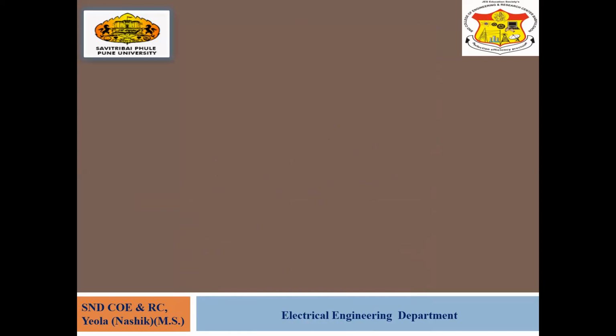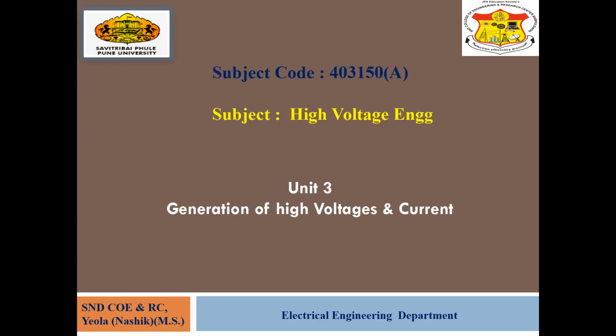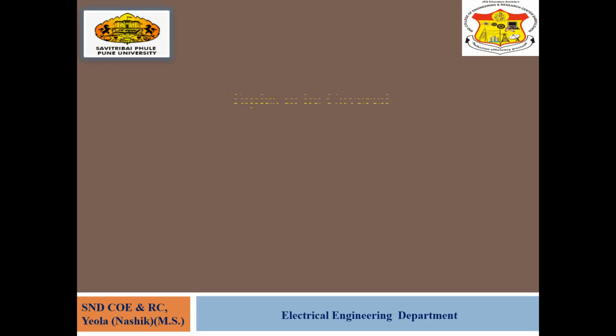So, in the last lecture we have seen the half-wave doubler circuit. It means the voltage is going to be doubled. Not exactly the same, due to the time constant of the capacitance, the voltage is somewhat less, so V output is less than 2 Vs maximum. But it is nearly double the voltage that is available. In the last lecture, what did you see?